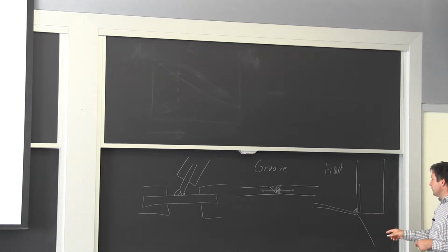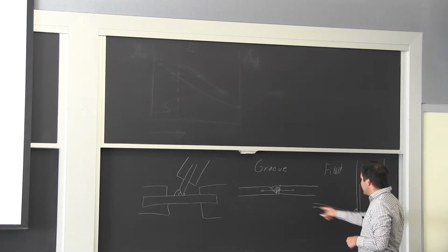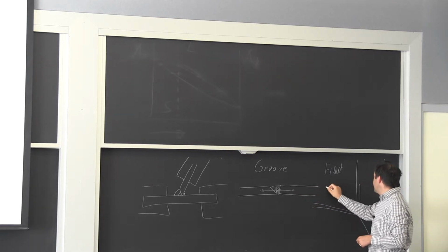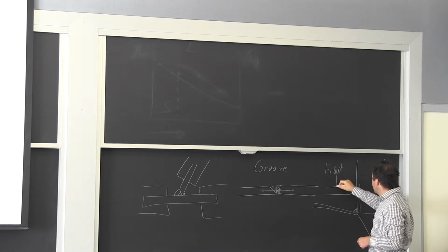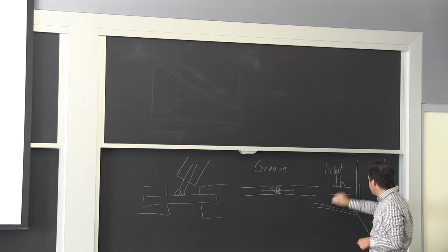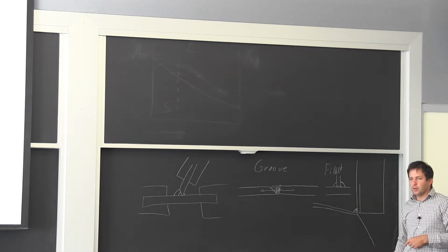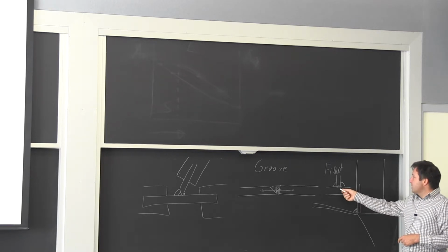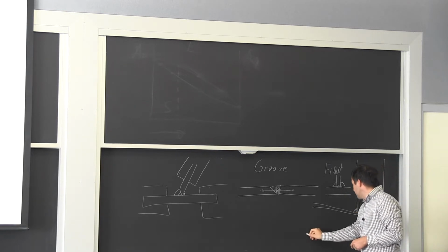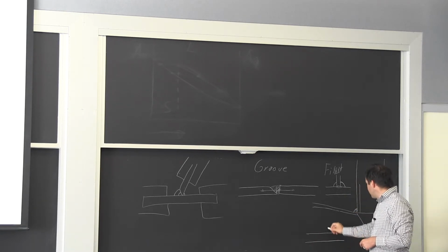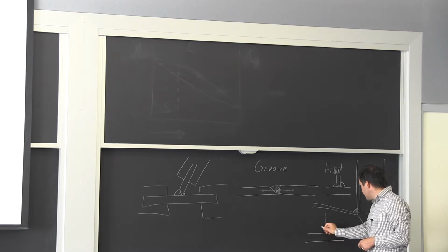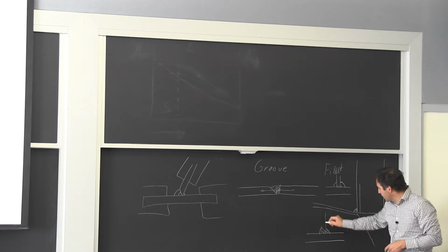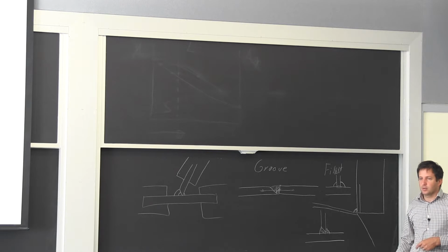The other example of a fillet weld is a T-connection. If I have a T-connection and I only use fillet welds, I don't have anything here, so I essentially have a crack in the metal because I didn't prepare it. So the fatigue strength of this connection is about half that of a T-connection with a groove design. The groove design lets me come from one side and fill it in, and come from the other side and fill it in. So I don't have a pre-crack in this configuration.